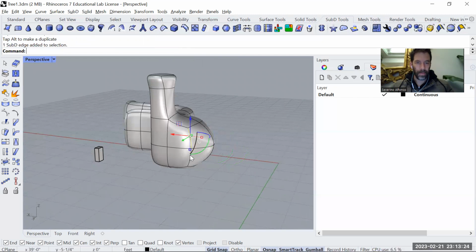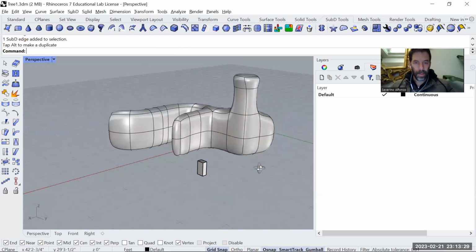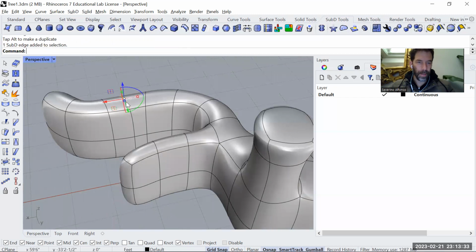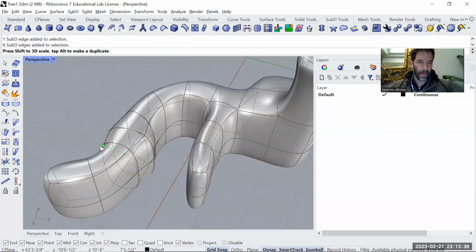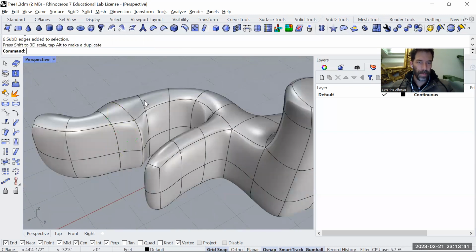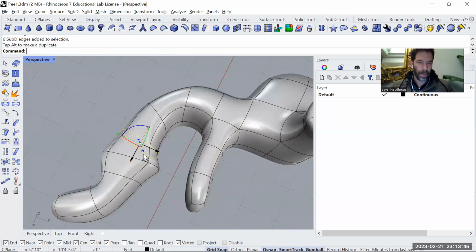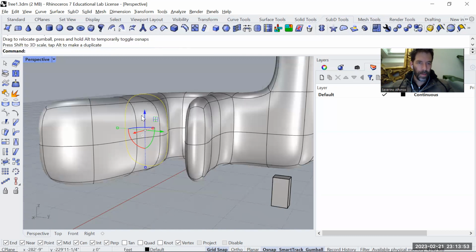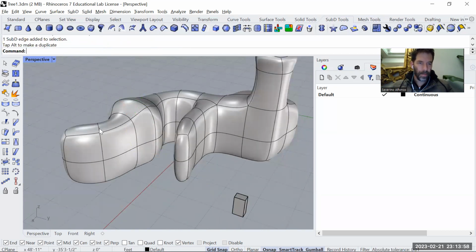You can Control Shift a couple of edges and move only the edges. You can Control Shift and select, by double clicking, the whole ring of lines. This is great, especially for tunnels. You can scale the tunnels and make them wider. You can do that for a couple of the cases, and you can reallocate, move them a little bit in this direction, and scale them. And then I can move one of the edges only above, so it goes upwards.